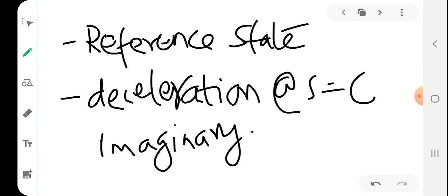You should be very clear that we are not at all decelerating the flow at any position in the flow path, but for the sake of study we consider what will happen if the flow would have been decelerated to zero velocity isentropically. What will be the properties? So that imaginary process refers to the stagnation condition.